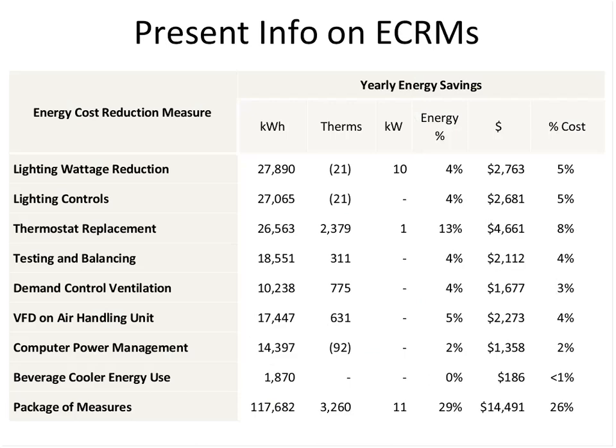So when we surveyed that building, we did an analysis, and this is what we came up with that we could do in it. Remember that building was fairly energy intensive on the electrical side. And what we found is that just putting better lighting in and putting some lighting controls in, the annual savings for those two alone were probably almost 55,000 kilowatt hours.